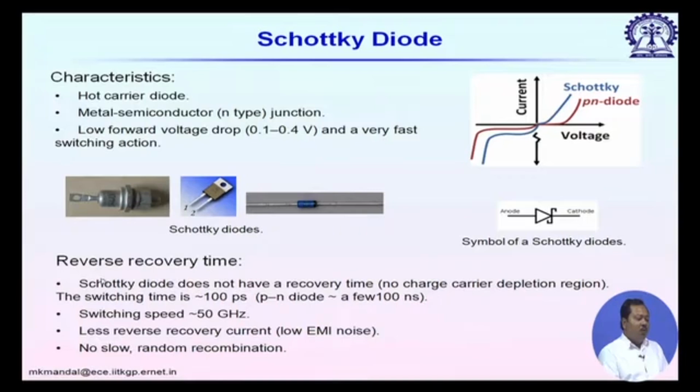So, why is it so popular at millimeter wave frequency? Because of very low reverse recovery time. Since it does not have any space charge region, there is nothing to recover from. So, that is why the recovery is almost instantaneous.